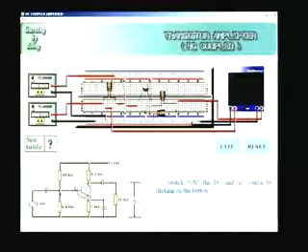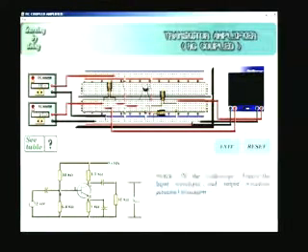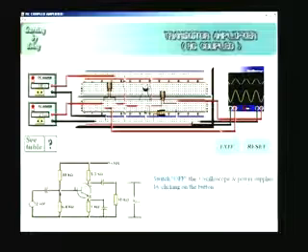So it is exactly the same as the circuit that is drawn here, which is also the circuit which you saw previously. And now let me quickly switch on the oscilloscope. Immediately you can see I have a 10 volt VCC and I give about 2 millivolts AC source at about 1 kilohertz frequency, and you can see the input signal is very small, and the output signal is very large, an amplified signal you get. So it is very easy to construct a simple RC coupled amplifier making use of a simple transistor and a voltage divider bias or whatever. In this case I have given an example using the voltage divider bias.